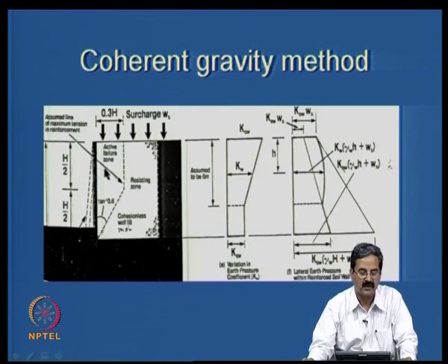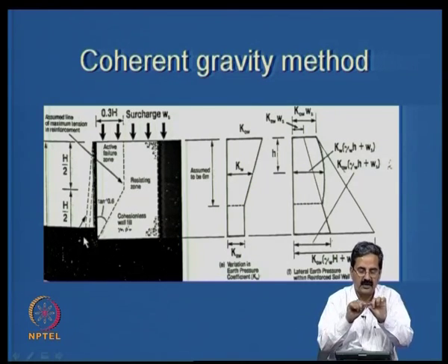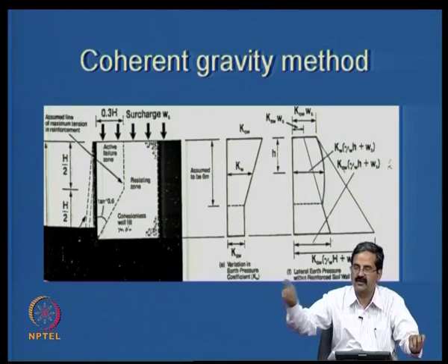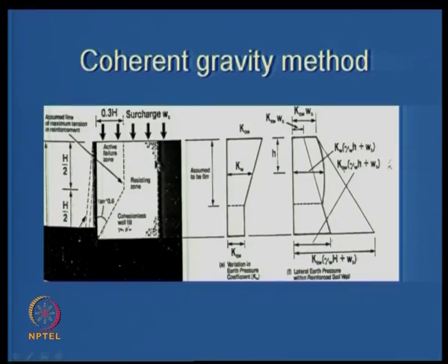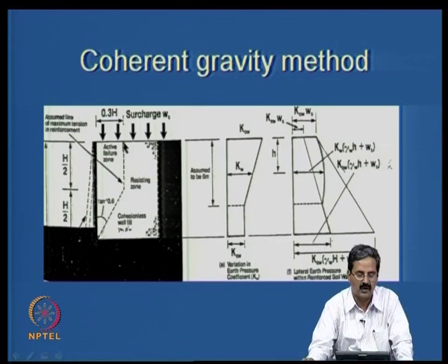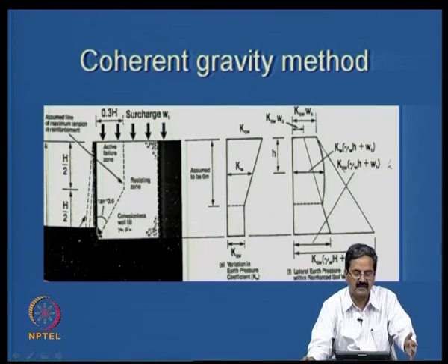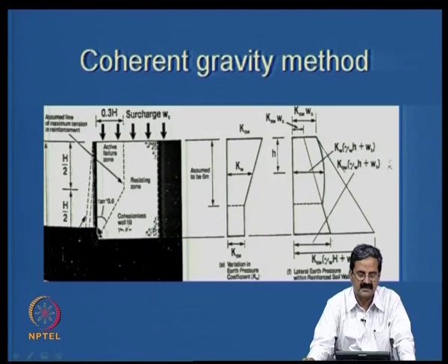If you observe for all the reinforcement elements where the maximum tension is, and then locate them and join them, you can find the distribution of tension on the reinforcement. As friction develops along this, there will be a strain mobilization, and all these points you can join. Even in FLAC analysis you can get that. So this is one important method that one should understand.